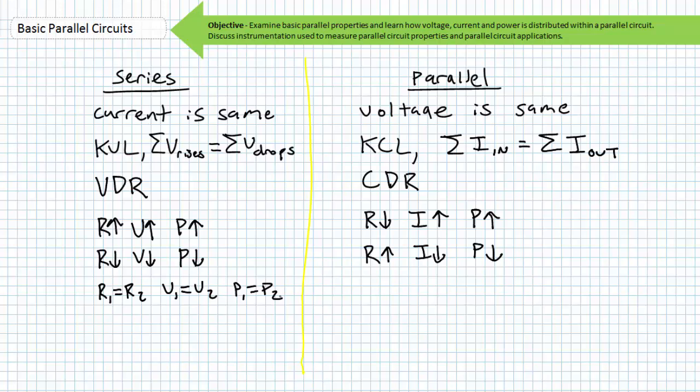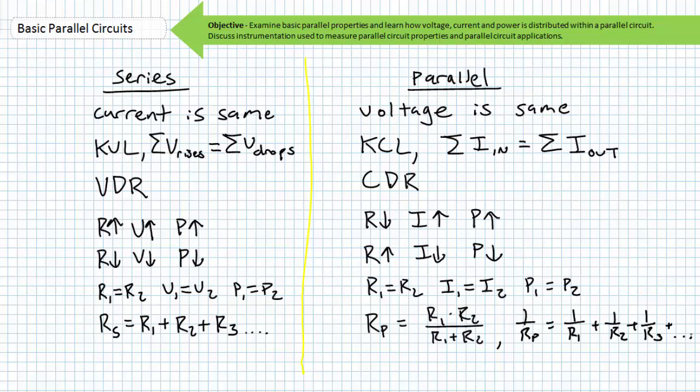Equal resistors in a series relationship have equal voltage drops and will dissipate equal amounts of power. Equal resistors in a parallel relationship have equal current draw and dissipate equal amounts of power. Adding resistors in a series relationship decreases source current draw because the total resistance increases via the series summation of resistances formula. Adding resistors in a parallel relationship increases source current draw because the total resistance decreases via your choice of several parallel resistance formulas.